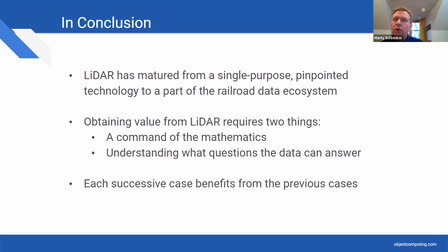But both for David's question and for Mr. Provenzano's question, what's the main advantage of these LIDAR applications over camera-based systems? The data volume definitely is a factor here, right? Because of course you've got a 2D image which has some attributes to it at the pixel level, versus each LIDAR point having relatively compact attributes.